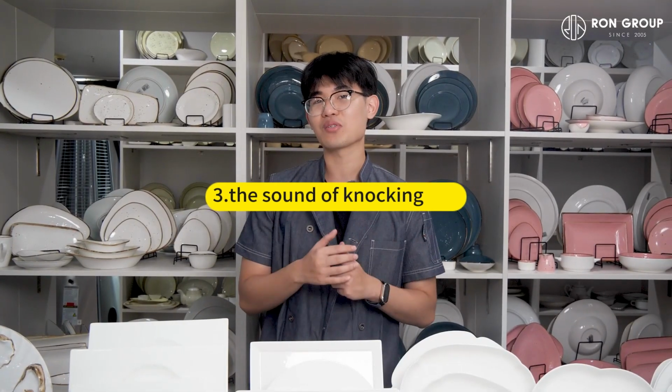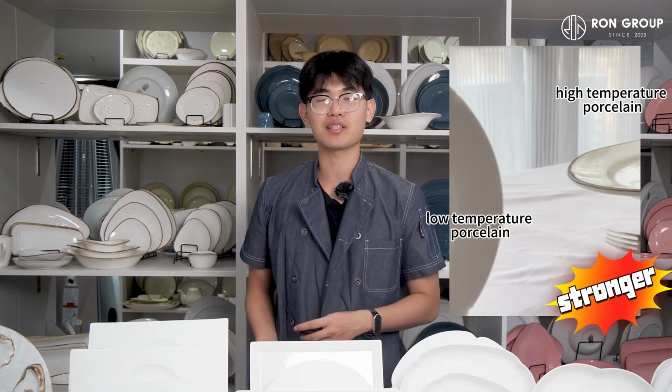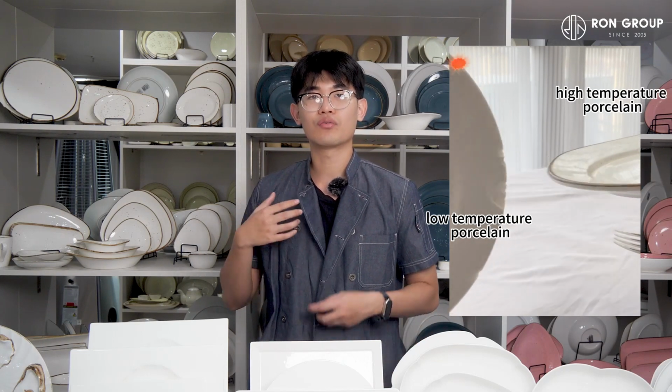Third, the sound of knocking. The sound of knocking on high temperature glazed porcelain is more crisp, and the sound of knocking on low temperature glazed porcelain is relatively dull. Fourth, the texture of the ceramic. The hardness of high temperature glazed porcelain is stronger than that of the low one, and low temperature glazed porcelain has more freckles.